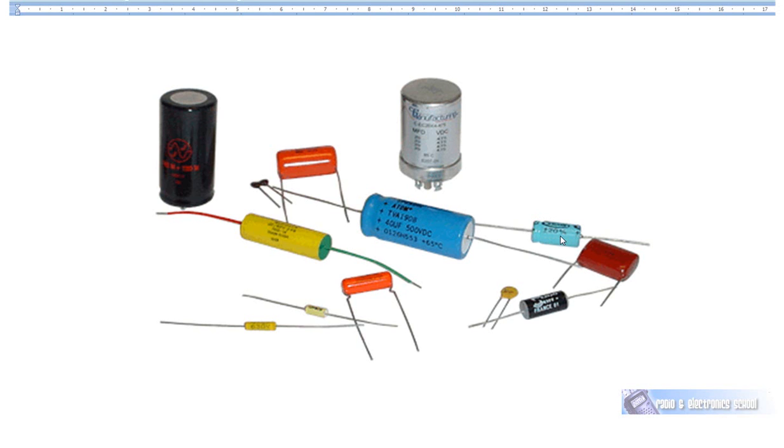And I've seen them explode with such force that the can the capacitor's in could fly across the room like a .22 bullet. I did this once in a practical demonstration in a classroom, and I deliberately reverse polarized a capacitor like this, and it exploded, and the aluminium can flew across all the students' heads and left an indentation in the rear wall. Needless to say, I haven't done that again without a bit of perspex in front. But electrolytic capacitors are dangerous if you connect them the wrong way around.